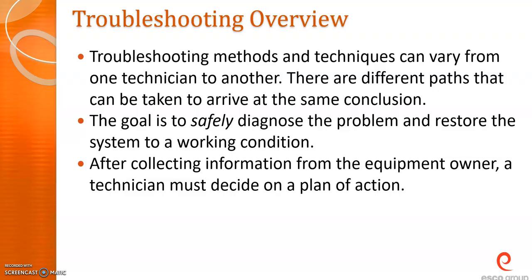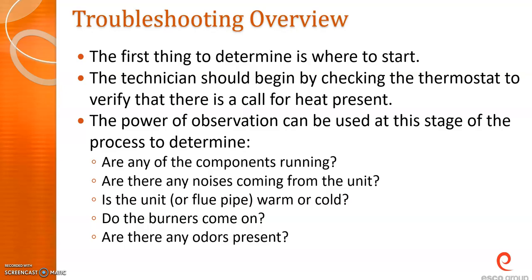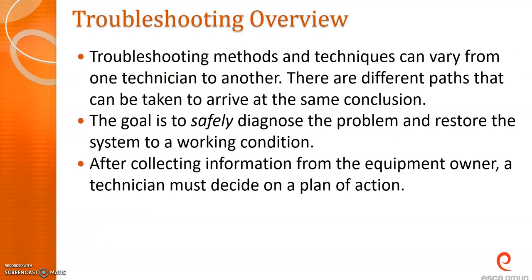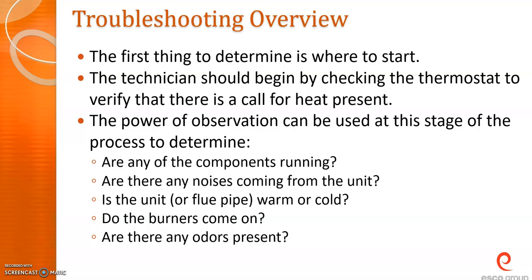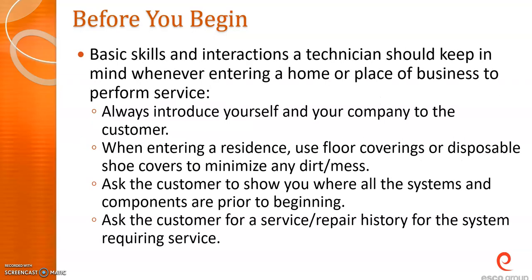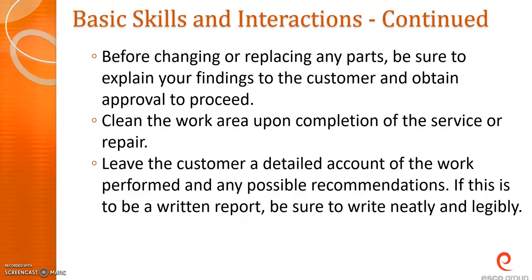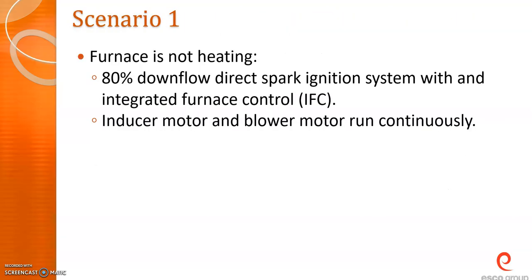So as we talked in the last video, one of the bigger things to understand is the difference between switches and loads. You need to understand that troubleshooting chart, the flow chart, that's going to walk you through your process, knowing what starts when, and then if it doesn't get to the next step, where to go from there. I'm going to go through a few scenarios just to show you how you'd approach this. Obviously, this is just from a paper, so being in front of a furnace is going to be a lot better, but at least it shows you the process.